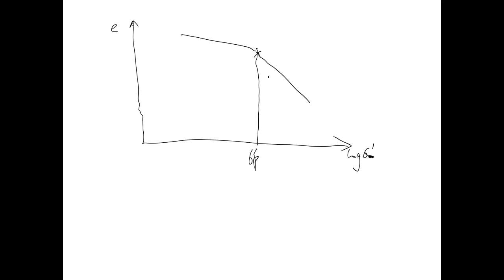So the values that we calculate are against the void ratio? No, it's one value. That's the one you calculated. Let's say originally the line is already there, always like this way. And then you calculate your sigma P prime. So then you know this turning point, that's the sigma P prime.